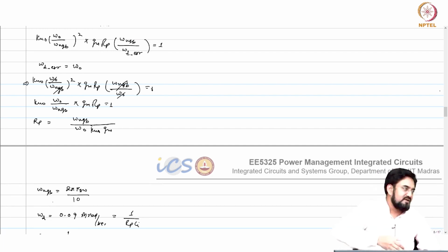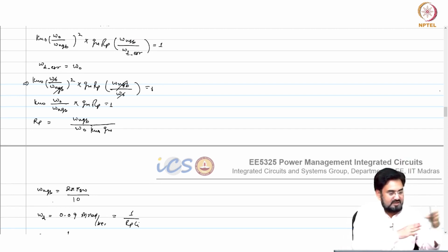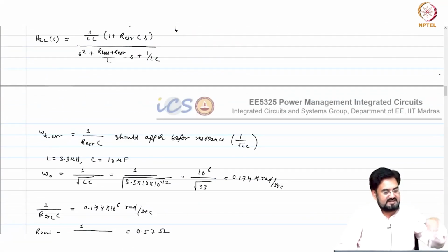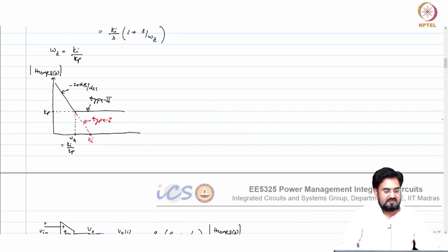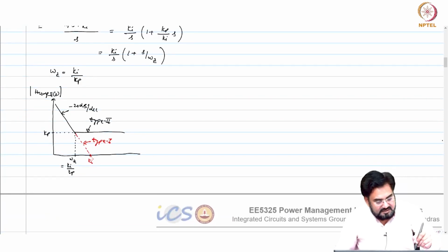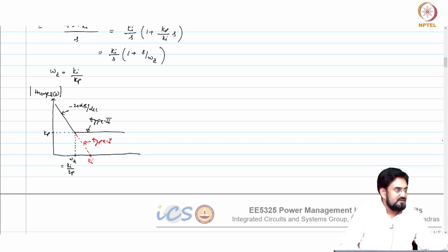So closer to your first order, minus 20 dB per decade, a very nice falling gain response, you will get the best response out of that. But if you move your zero to very low frequency, your flat gain is changing here. So this guy, if I move it here, zero here, then ideally I want this to keep falling to look like a first order. So your settling response may not be as good as first order in that case. So that is one thing.